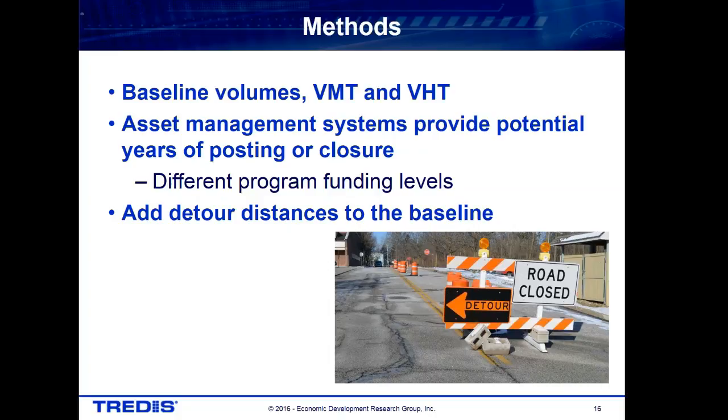There are many ways to set a baseline, such as keeping the network fixed in its present condition or state, using a baseline where full engineering needs are met, or setting a baseline that reflects planned or expected changes to the future network. Explicitly defining a baseline over the entire lifetime of the analysis is important for developing useful comparison cases. We recommend including total system travel in the baseline rather than only looking at travel impacts relative to a level of zero change, because establishing a complete baseline of all travel helps to assess relative impacts of your programs.